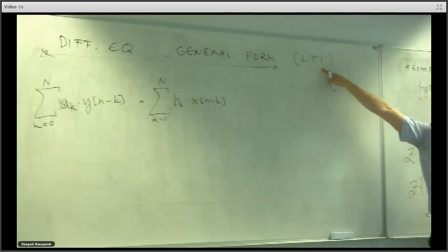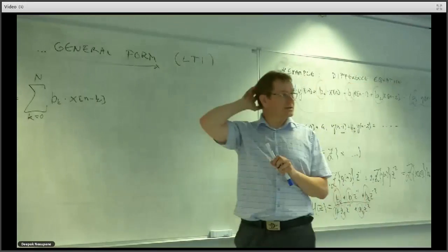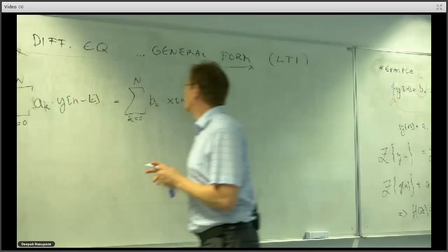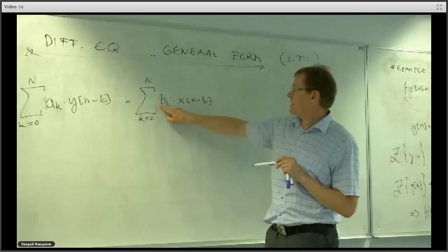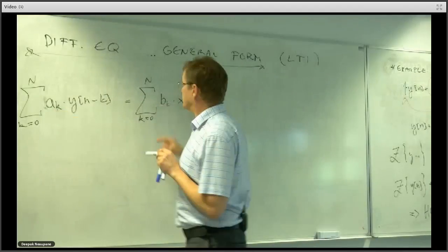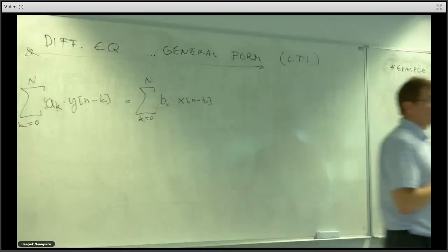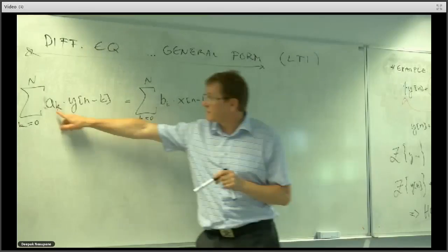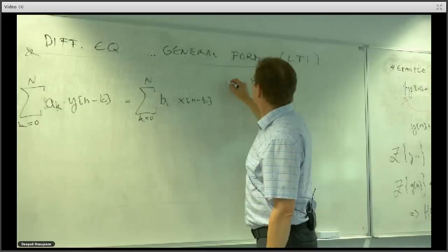Linear time shift invariant. I don't know if it's causal yet, and I don't know if it's stable yet. Fundamentally, it is causal if there are no non-zero scaling factors on the input before the first non-zero scaling factor on the output. Okay, that's the general form.